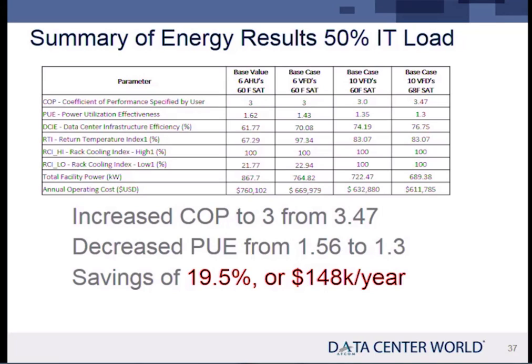I have to get close to see it. And then we raised supply air temp just a little. Now, when you go up on supply air temp, the fans start to come up a little bit because they're sensing max temperature. And so that ended up being a wash with respect to cost. We went from 632 down to 611. And that's because the efficiency went up. Now, again, the efficiency of the heat rejection system went up because it was getting higher return air temps again.